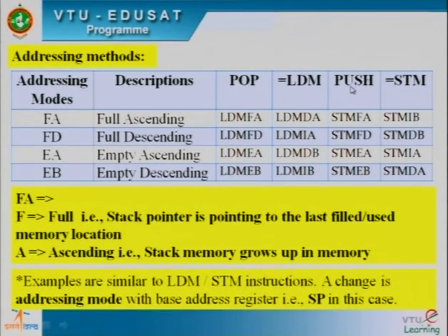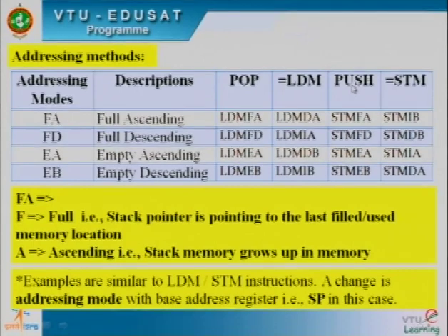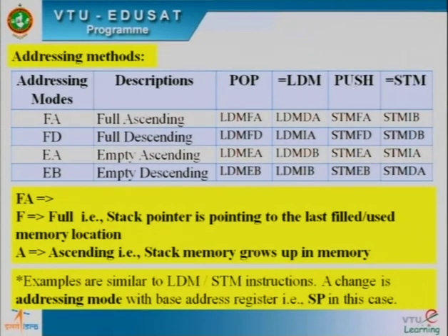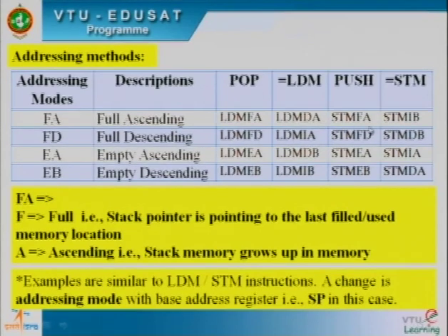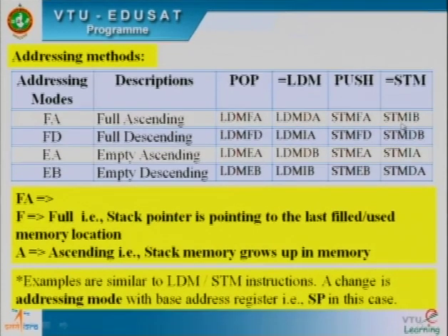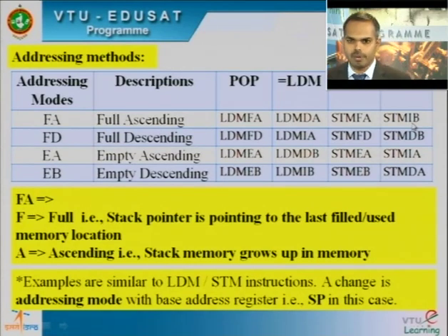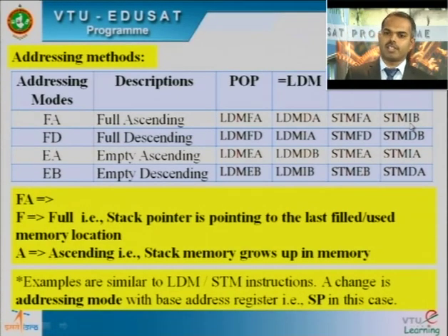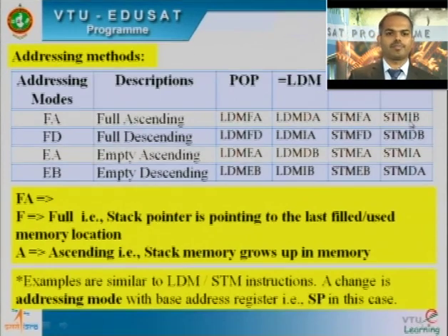Now the push instruction. The push instruction is like you are pushing the register value to the stack memory. With that, again, STMFA, that is full ascending stack. With the help of the full ascending stack, store the register values in the full ascending stack. That is the meaning of STMFA. This STMFA instruction is executed internally with the help of STMIB, that is store multiple registers and increment before.